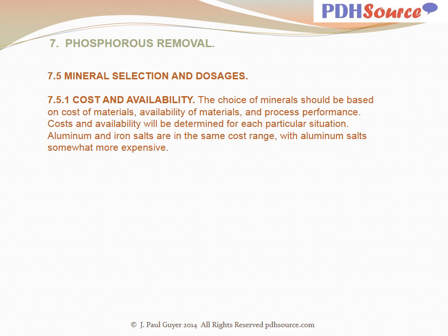With regard to the cost and availability and mineral selection and dosages, the choice of minerals should be based on the cost of the materials, availability of the materials, and the process performance. Cost and availability will be determined for each particular situation. Aluminum and iron salts are in the same cost range, with aluminum salts somewhat more expensive.